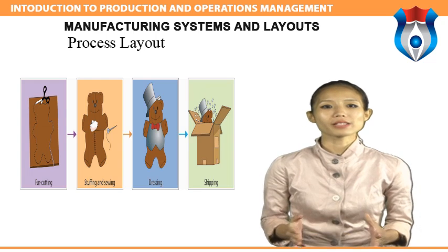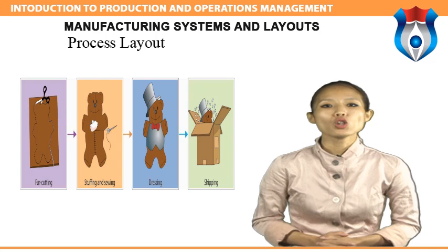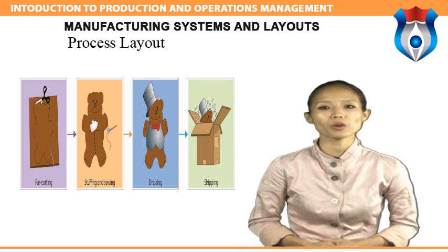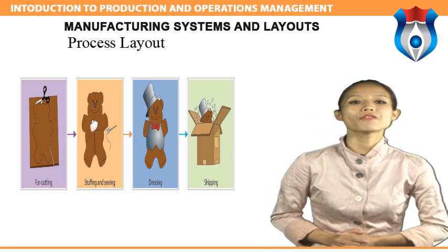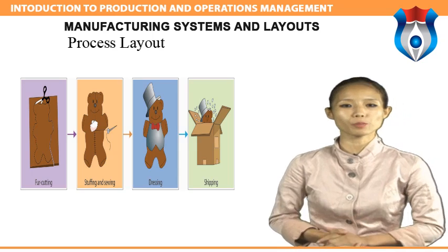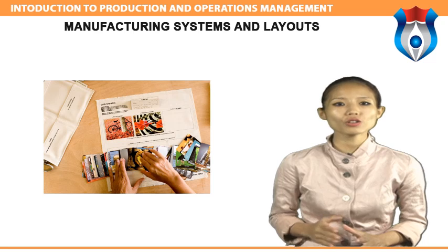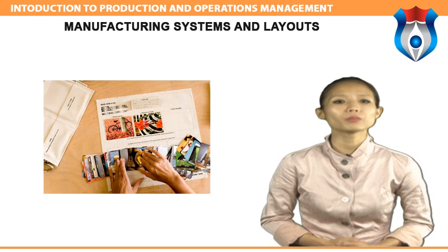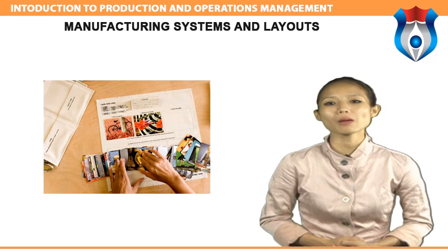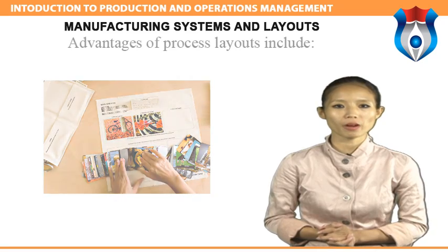Process layout. Process layouts are found primarily in job shops or firms that produce customized, low-volume products that may require different processing requirements and sequences of operations. Process layouts are facility configurations in which operations of a similar nature or function are grouped together. Improving process layout involves the minimization of transportation cost, distance or time. To accomplish this, some firms use what is known as a method grid, where subjective information is summarized on a grid displaying various combinations of department, work group or machine pairs.